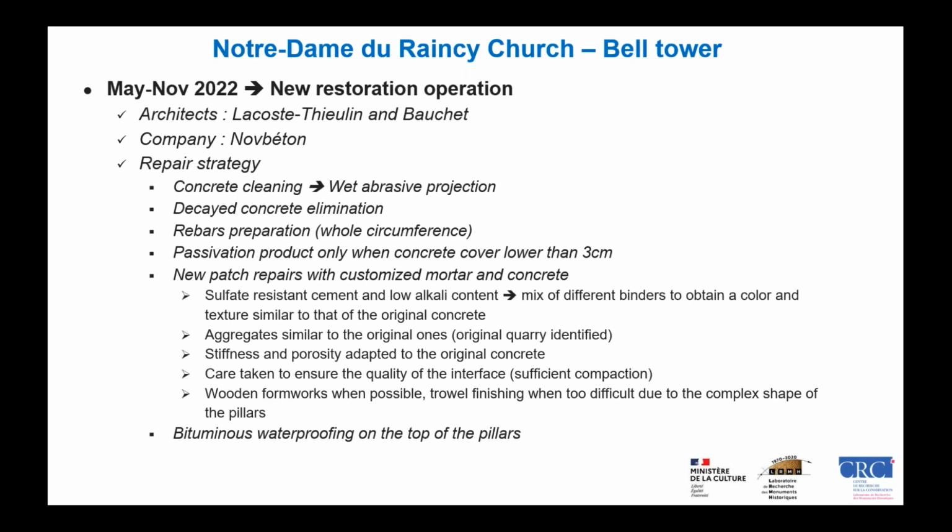sulfate resistant, as we had seen that there was sulfate pollution on the concrete, low alkali content because the aggregates were reactive to alkali, and there was a mix of different binders to obtain the color and the texture similar to that of the original concrete. The aggregates were the same. The original quarry was identified. Stiffness and porosity were adapted to the original concrete, and care was taken to ensure the quality of the interfaces with sufficient compaction.